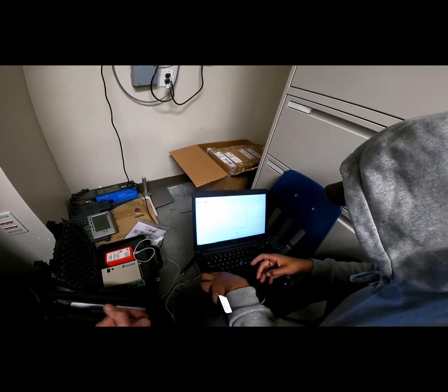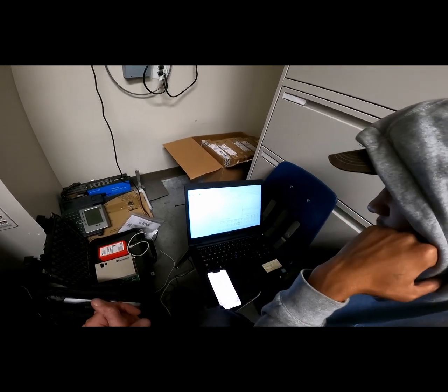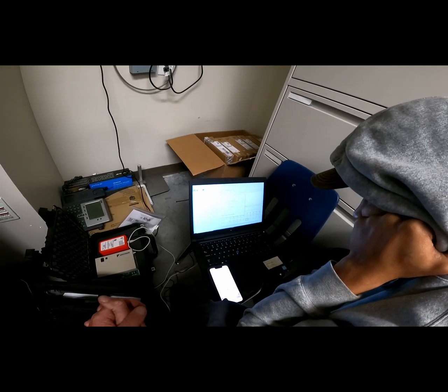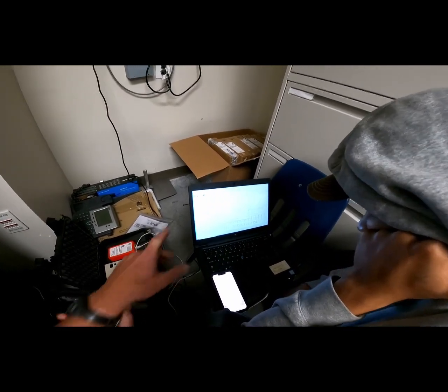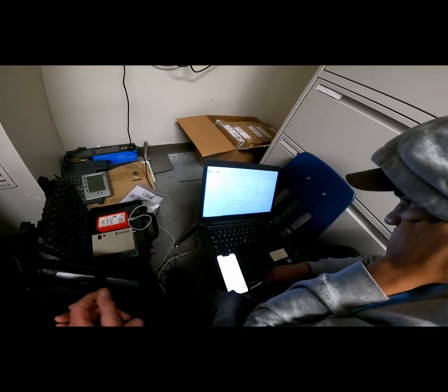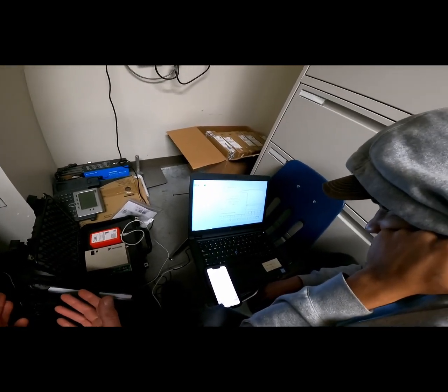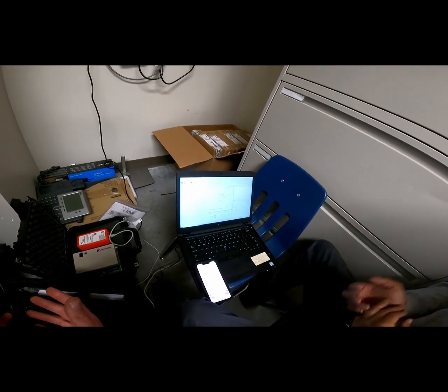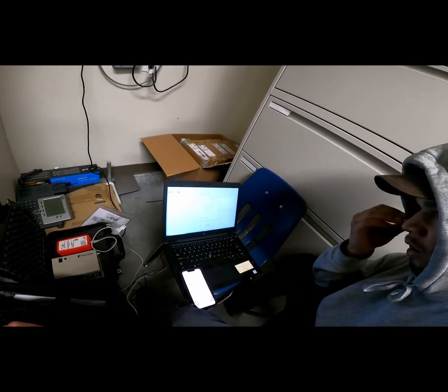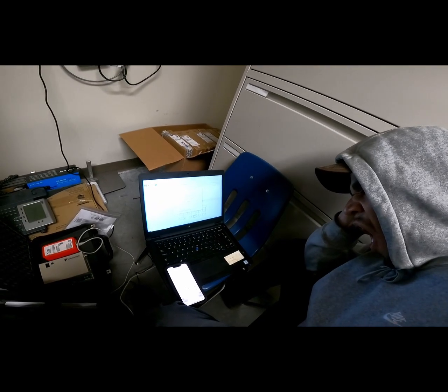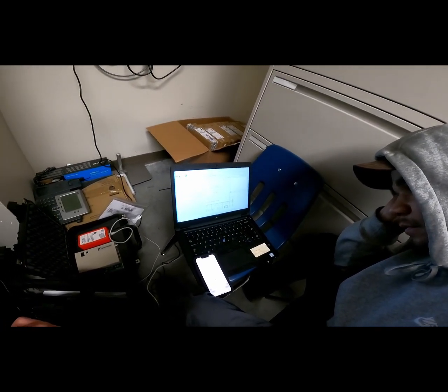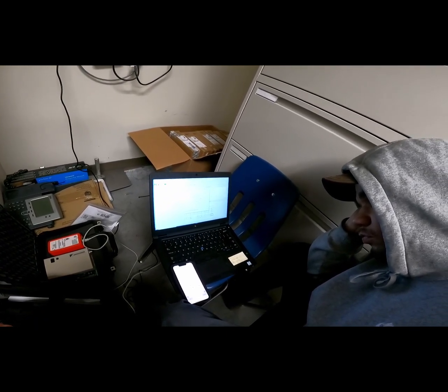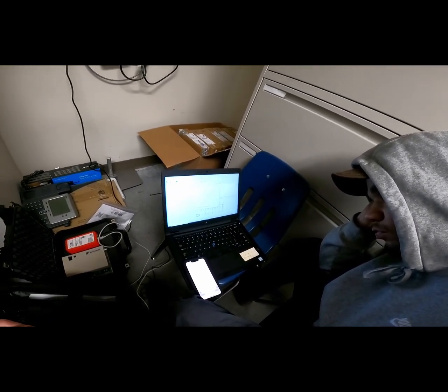Now what it's picking up now are the remote controllers, essentially the thermostats that are tied to each one of those indoor coils. Now some of these indoor units are going to be ceiling cassettes. They could be normal evaporator heads, like on a mini split, or they could be a ducted fan coil, basically an air handler above the ceiling that's got ducts coming in and out of it. They're the ones that I changed the pleated filters on while you were pulling the mesh filters out of the cassettes. Okay.